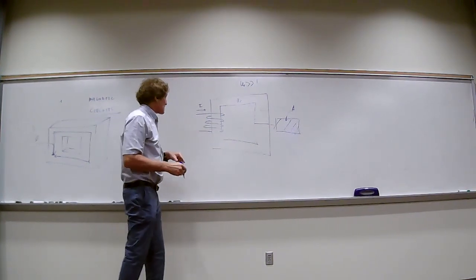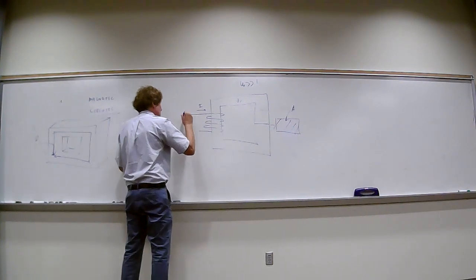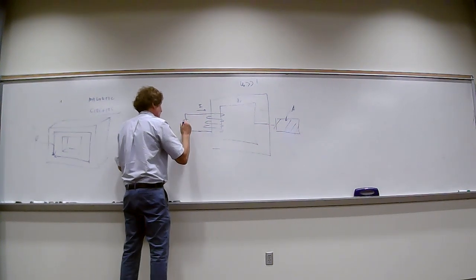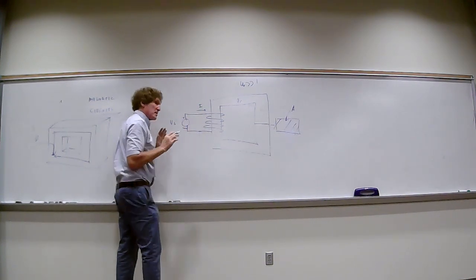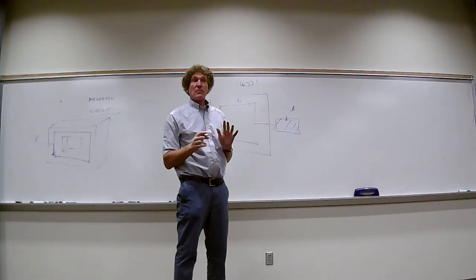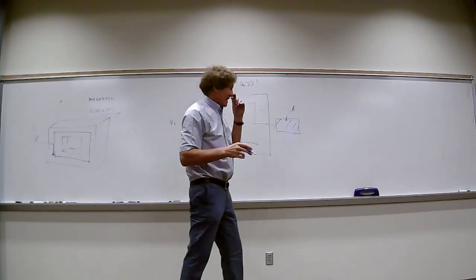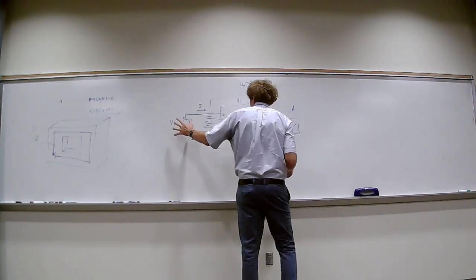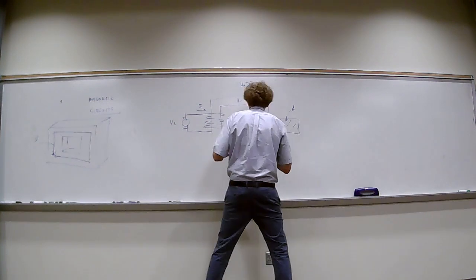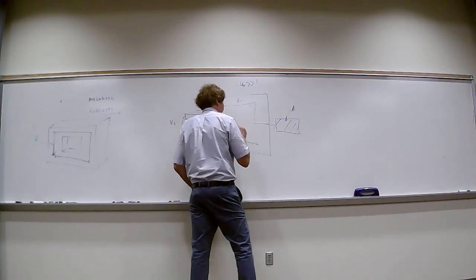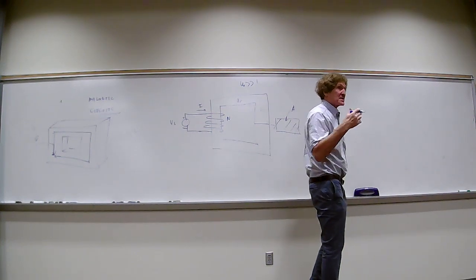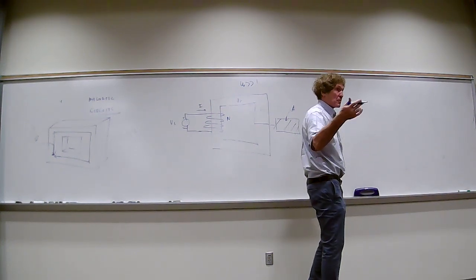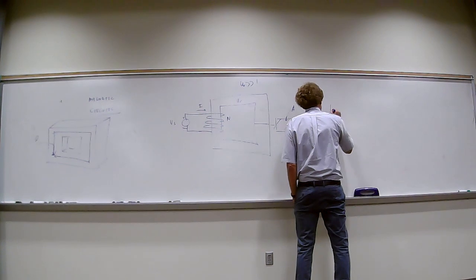Now we build the analog for this. If you have a voltage here, Vs, it will cause this current. You don't need to worry any more than that. Now, what we say is this current and the number of turns, which I'll call N, is called a magnetomotive force. It's like an electromotive force or a voltage. So the magnetic circuit looks like this.